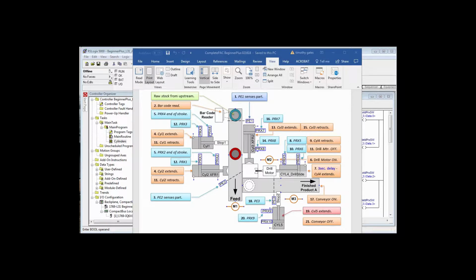And then we turn the conveyor off because there's no reason to leave the conveyor running, wearing any finish off the bottom of that part. And that's basically the end of the process right now. There's a lot more to it than this, but this is sufficient to get you going. And you see the 5 cylinders there, cylinder 1, 2, 3, 4, and 5. You've already created the relationship between the single solenoid that tells them to extend and the time delay before it says they're extended or retracted.